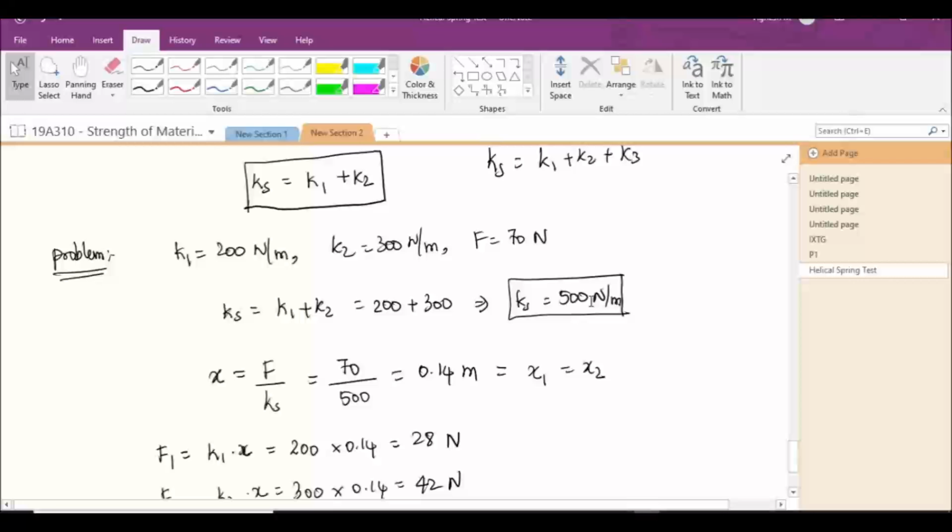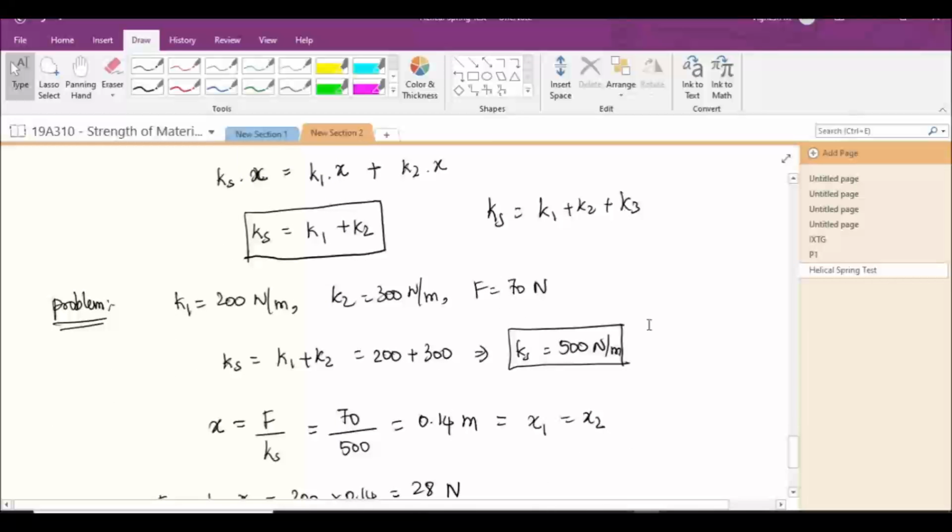Okay, we have two coil springs attached: one outside coil spring and one inside coil spring. So in a suspension system, two coil springs are used, both present one inside the other. So these are in a parallel condition. That's an example of the parallel condition, in which the stiffness of the spring is more.